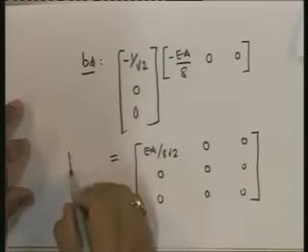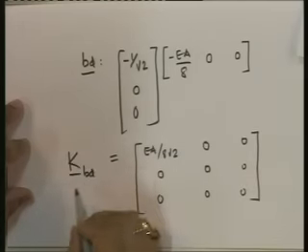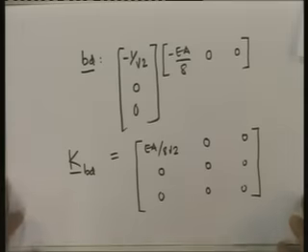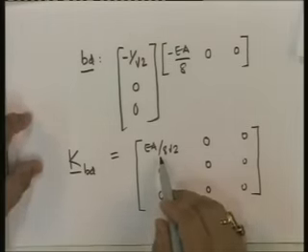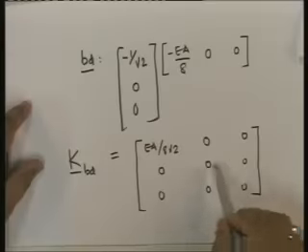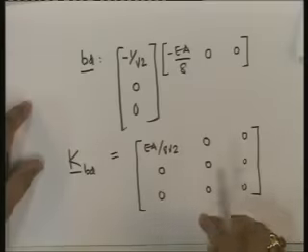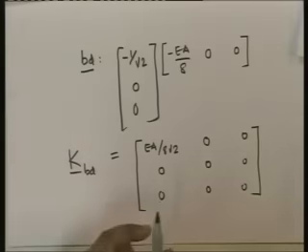Why do you think that is? That is the contribution of BD to the stiffness matrix. Because if you look at it, what does this mean? That it only provides a rigidity towards R1. That's true, because when you have R2 and R3, the bracing member does not deform and does not provide any.